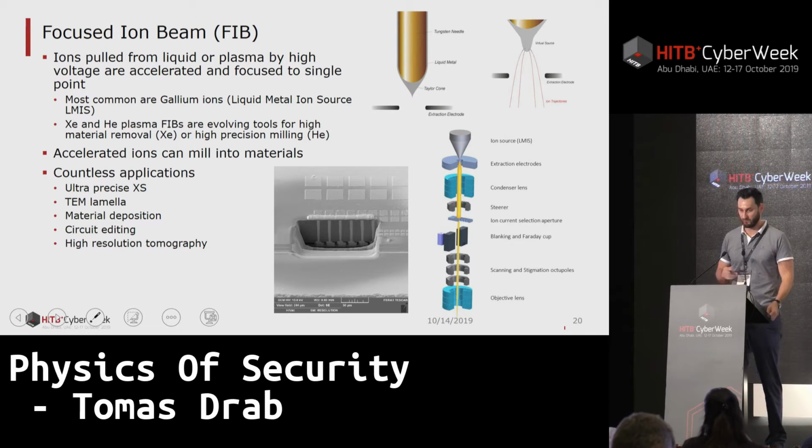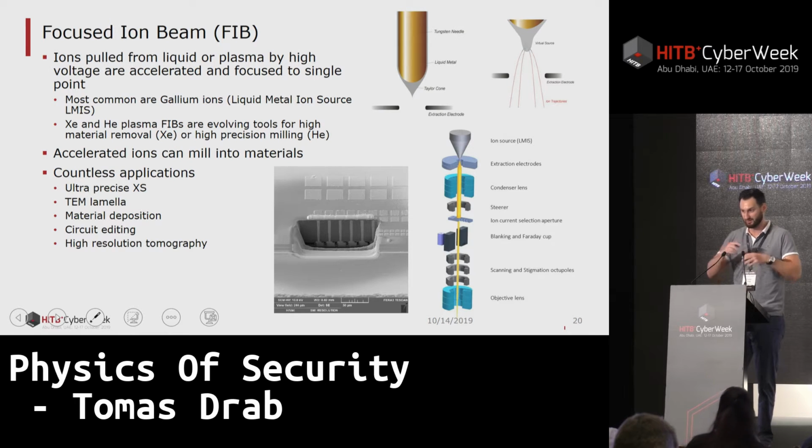So imagine if you want to create some connection into the deeper structure. First you create a hole in a chip to gain access to the trace. Then you can fill it with tungsten, for example, and create the probe landing site where you can then microprobe the chip and sniff some data.